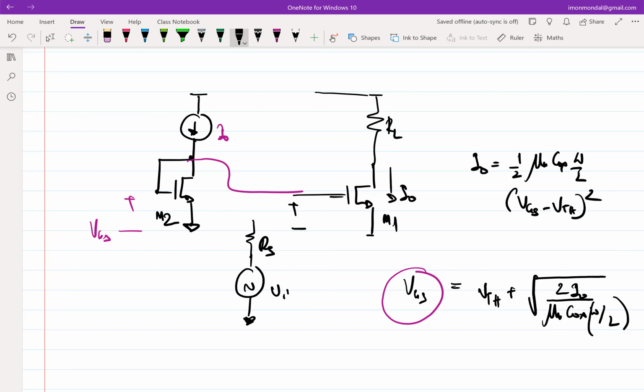What should I do? So I can connect it like this. Can I connect like this? Okay, what's the problem if I connect like this? Yeah, VI is 0 with DC. VI is a sinusoid, so it doesn't have any DC. Let's say VI is equal to VP sin omega t.